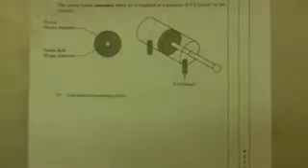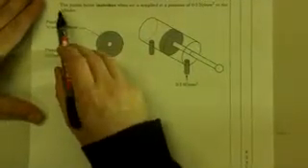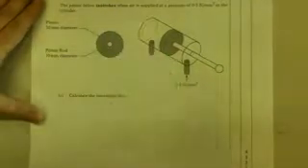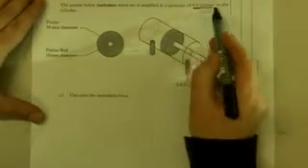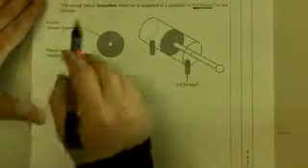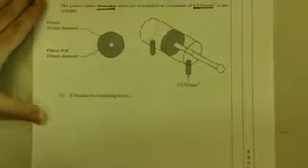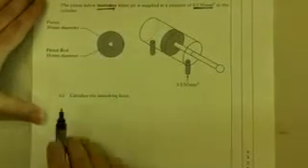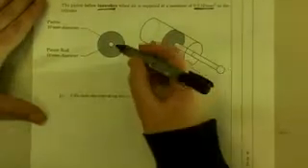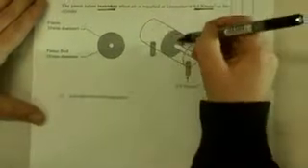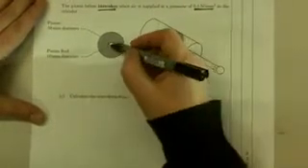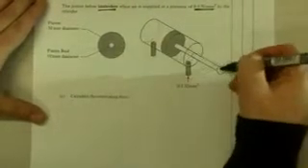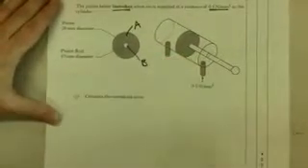Okay, look at the second part of the question now. Here we've got the diagram of the cylinder that outstrokes and instrokes, and we're asked, the piston below instrokes when air is supplied at a pressure of 0.5. So we've got pressure there, and we're looking for the instroking force. Okay, so it says calculate the force. Well, first of all, I've got two areas. I've got the area of the cylinder, and then I've got the area of the rod that comes out of the cylinder. So we'll call that area A, and we'll call that area B.